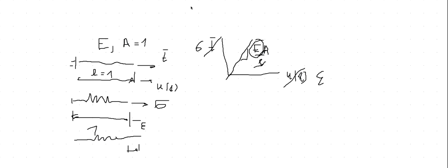Now we can do something called viscoelasticity, because this is already linear elasticity. The most general case of linear viscoelasticity is the one where I can have one spring, and then in series connection, I can connect this with a second spring. And here I can put a viscous damper.